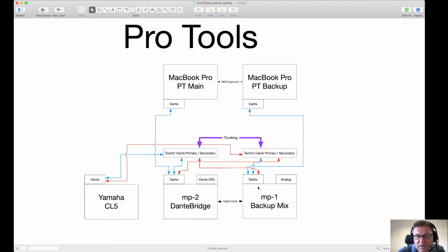This is where, through the switches, thanks to the fact that those 2 ports inside of the Prodigy Dante card are like in the same switch, the primary of the computer is forwarded towards the primary and primary with the trunking system between the 2 switches. The 2 switches were connected in trunking mode with the tagging of the several VLANs by means of a stack of switches, both primary and secondary. But pay attention: the primary in this switch has been connected while the secondary was connected to the other switch, to prevent failure of the same switch breaking both primary and secondary of the same Dante card.